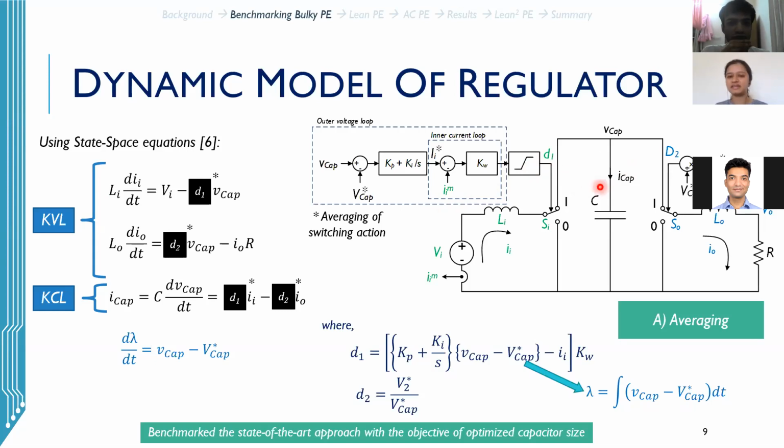Okay, for the DC bus cap. And any changes in the load are going to be adjusted by the duty ratio D1, such that the capacitor voltage is regulated. So that's the idea, right, for designing the input control loop. Yes, of course, it is hierarchical. So the question is, the input control loop design is already going to be stabilized. For a given value of cap, you design Kp and Ki such that the input loop works stably. Correct? Yes. Right. So what is this condition that you had just now elaborated?